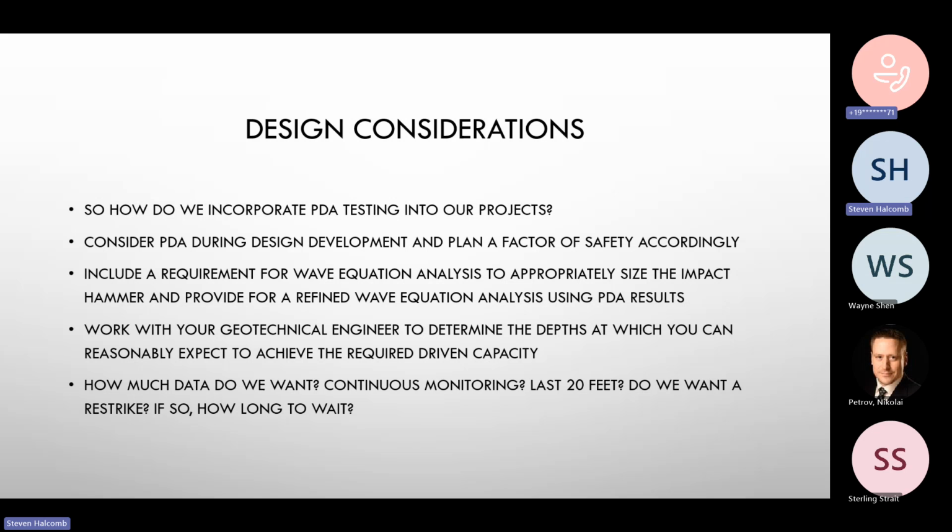Maybe look at some numbers in terms of cost and say, well, would something like PDA help save cost, or where the IBC calls for the requirement to actually do it, because there is that section in 1810 that does say you have to do it under certain conditions. You can also do a pile load test, but like I said, we don't generally do that.